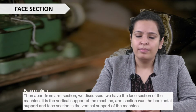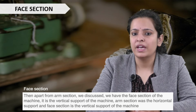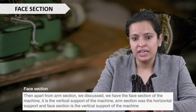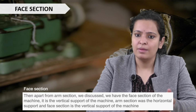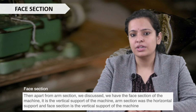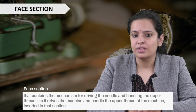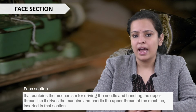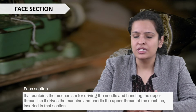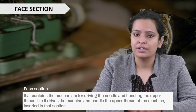Then apart from the arm section we discussed, we have the face section of the machine. The face section is the vertical support of the machine. The arm section was the horizontal support, and the face section is the vertical support that contains the mechanism for driving the needle and handling the upper thread. It drives the machine and handles the upper thread that we have inserted.